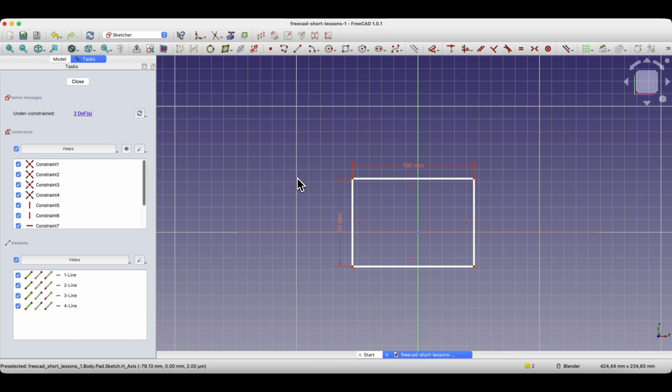When creating 2D geometry, on the basis of which we create 3D solids, it is worth striving to ensure that this geometry is fully constrained, meaning we aim to remove all degrees of freedom. Of course, if we do not do this, it is not a mistake. In the case of simple geometries, this may not matter much, but in the case of somewhat more complex geometries, if these geometries are not fully constrained, we may accidentally damage the sketch. This may affect the later stages of design, especially if we are designing a part in several or a dozen stages.